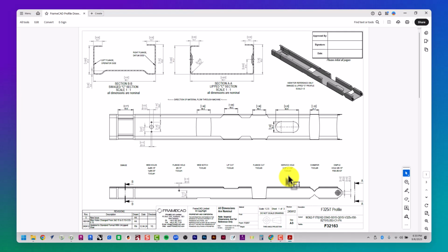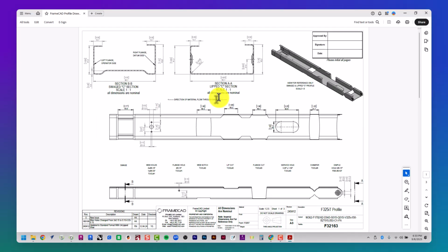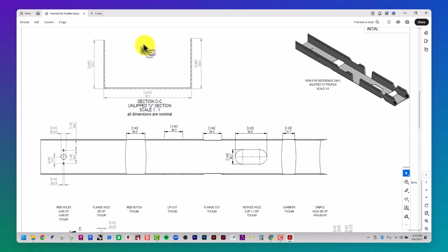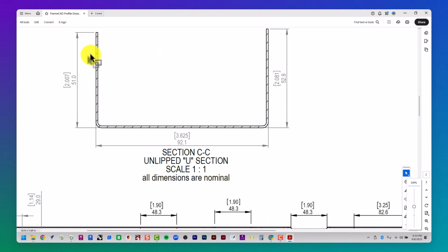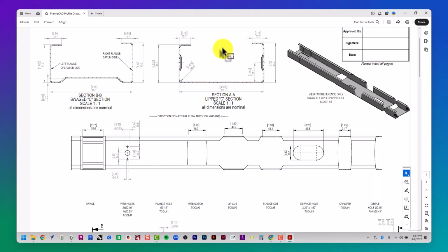This right here is called a C section, and I can also produce this one here, which is a U section. Okay, this is a C because it's got these little hooks over here, and it kind of looks like a C that's laying down, right? And then obviously the next page shows the U section, which looks exactly like a U. So those are the 2 different types of sections I can produce on this machine here at school. The C section is also called an S section sometimes in the industry.